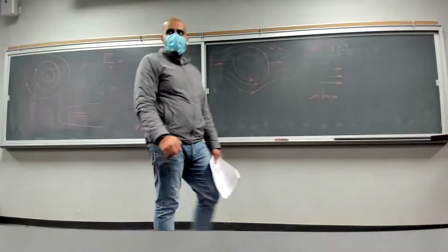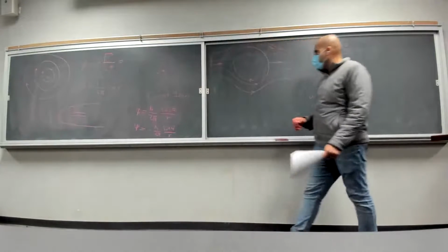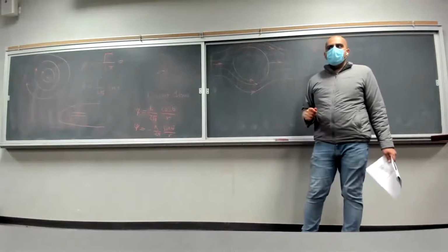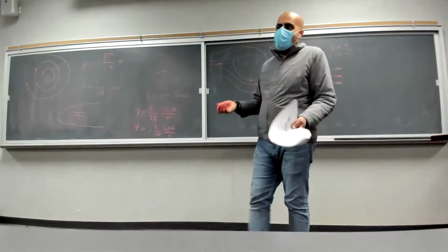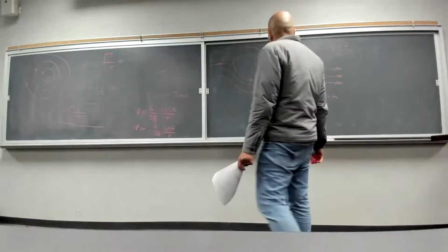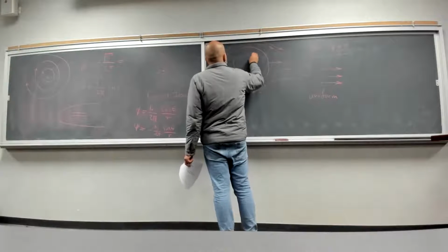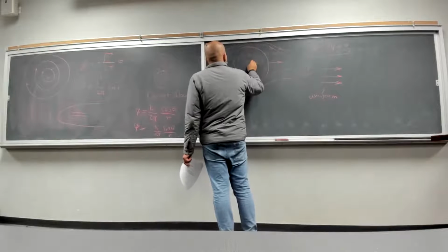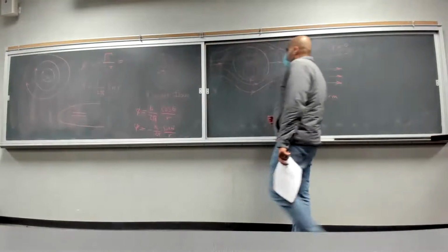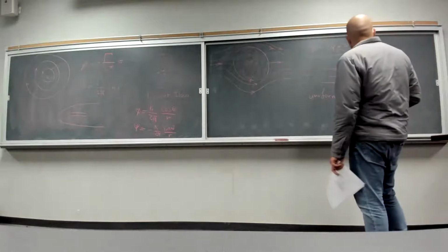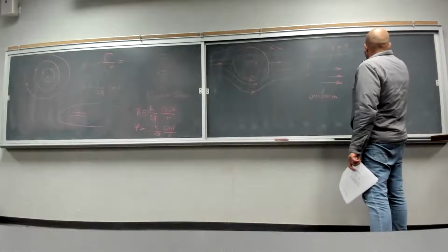So we want to get a type of elementary flow that's going to give us a stagnation point here, same velocities here. Doublet flow, that will be the only other option, right? Which is true. So if you have a doublet flow, you are going to get flow past the cylinder.